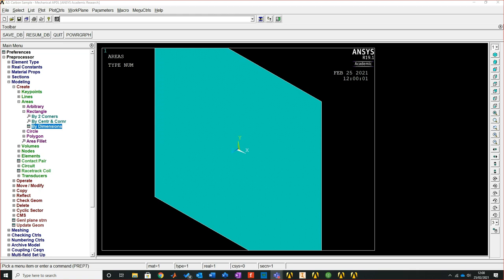However, bear with me, because when we shift over to Workbench, we're going to be able to complete this far quicker. The reason is with this, you tend to try and build your samples in here. You never have detailed geometry in here. You tend to have small sectional pieces, pipe sections, sandwich configurations, things like that. This allows you to look at the layout and the procedure you're using, and then look at what this material will do under certain conditions. However, if you wanted to move towards assemblies, this is where you start to move away from using APDL and use Workbench. Hence why we're going to move in that direction.